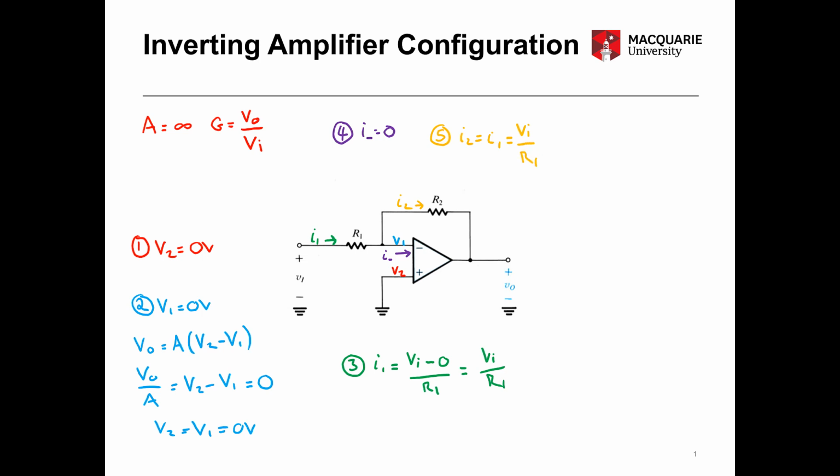So that brings us to the final step of this circuit analysis, and that is to work out V out. So we know that our output voltage is going to be the voltage at the V1 point on the left of R2 minus the voltage drop across the resistor R2. So minus I2 R2.